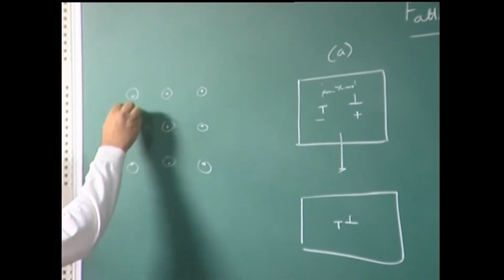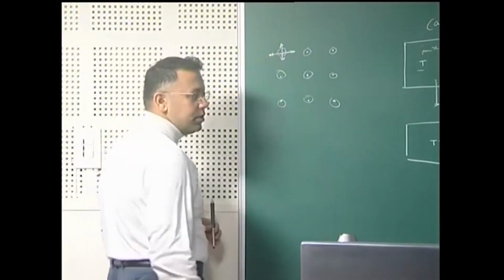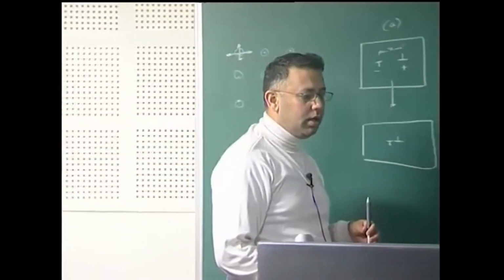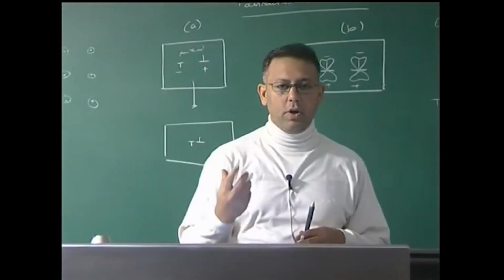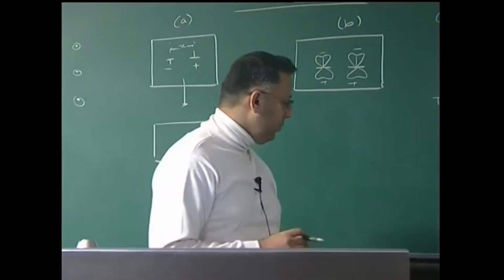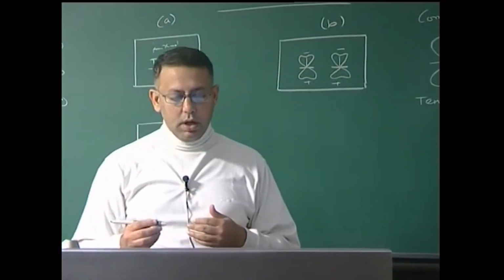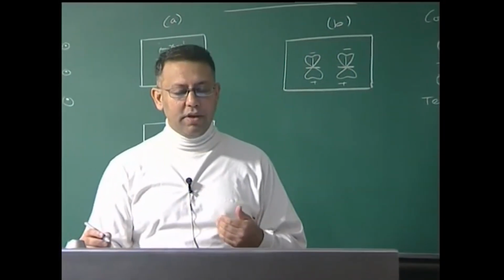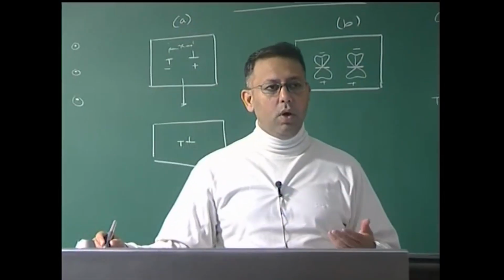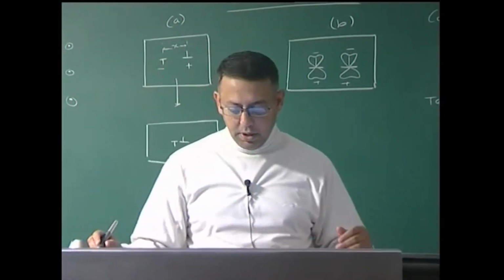So, therefore, atoms are vibrating about their mean position typically in all 3 dimensions. Therefore, I can see that this concept of a perfect order or a perfect lattice, with an atom at every lattice site, is actually violated, and because of this, this becomes an unavoidable defect. As we know that we always have materials above 0 Kelvin, therefore, this would be another unavoidable defect in a material.